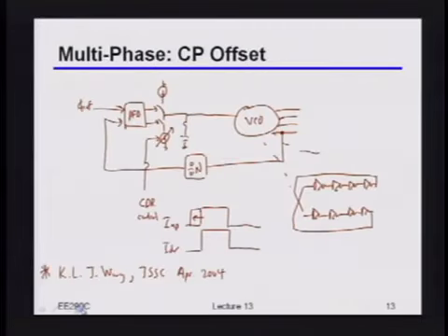So what's kind of painful about doing that in this particular design? Why does that kind of suck if you want to have the thing wrap? It's analog. It is analog, but let's be more specific. What would you have to do when the thing wrapped? Pick your current from high to low? Yeah, exactly. What you'd have to do is figure out the magic current level that, if I flipped it back from the high level to the low level, gives you exactly 360 degrees of phase shift, right?